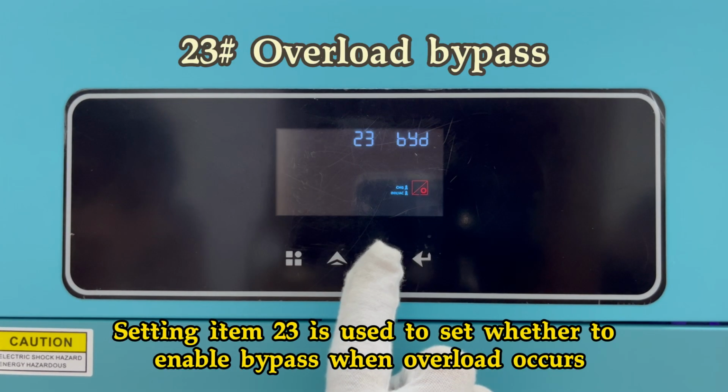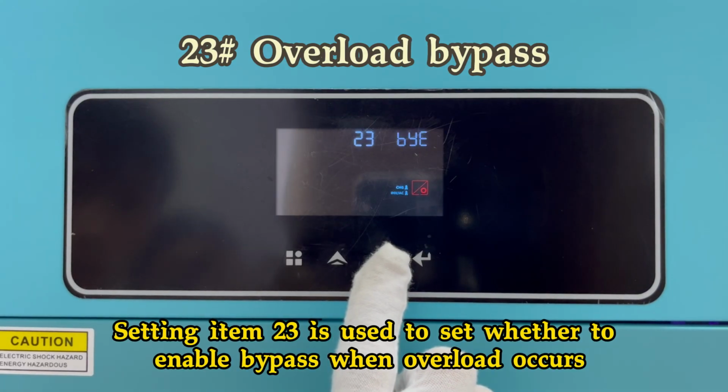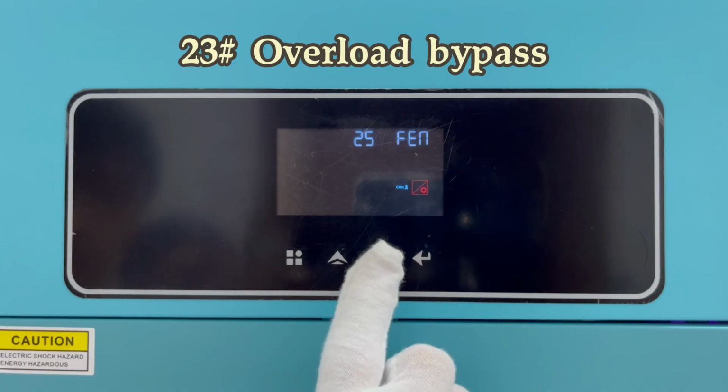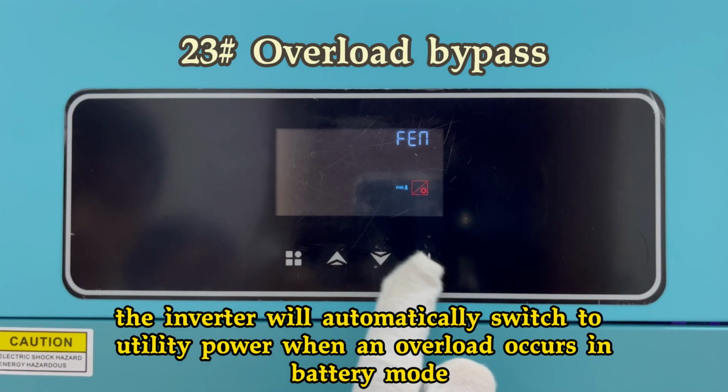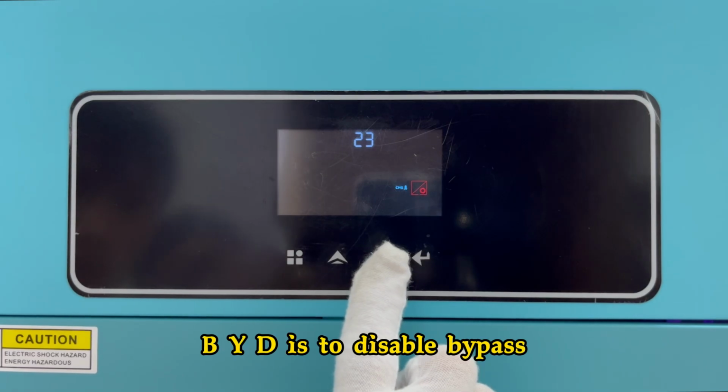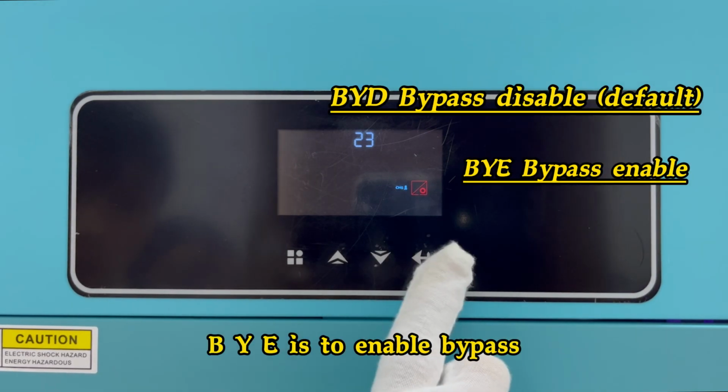Setting item 23 is used to set whether to enable bypass when overload occurs. If this function is enabled, the inverter will automatically switch to utility power when an overload occurs in battery mode. BYD is to disable bypass. BYE is to enable bypass.